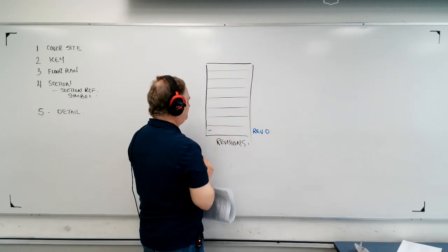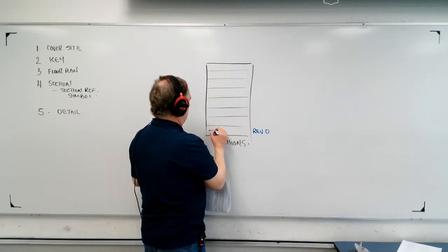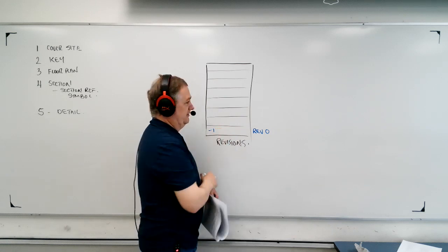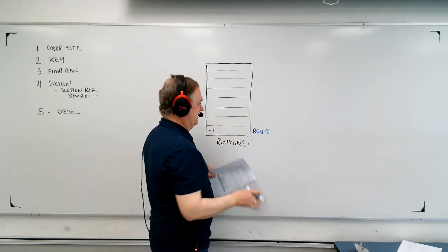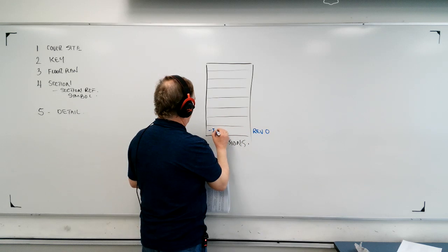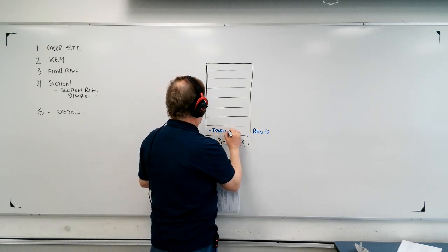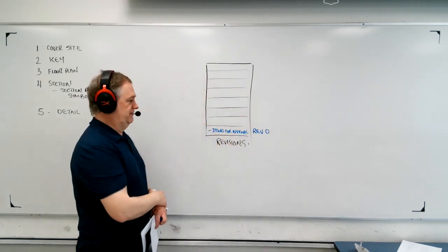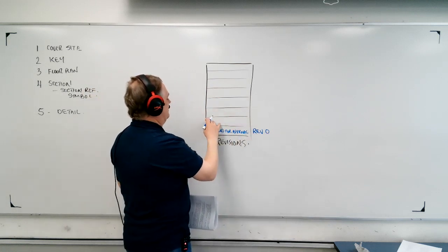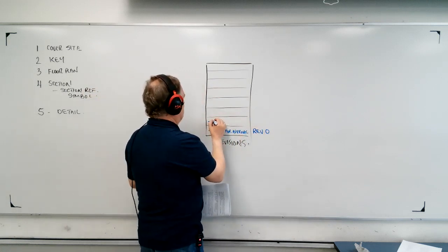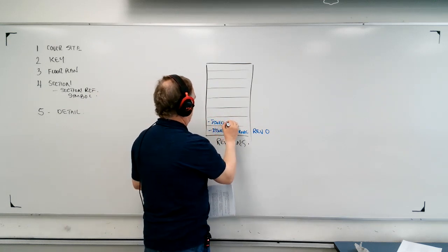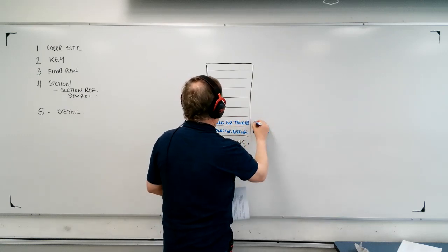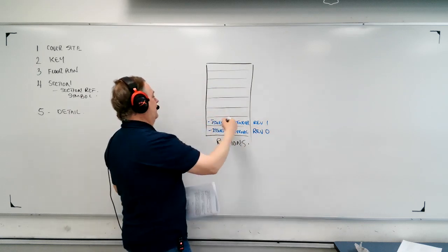And this will be, for instance, usually at the point where the engineers basically put everything together and put the plans together and put all their stuff in. So I would call this issued for approval. Quite often, the first revision is issued for approval. Then at some later date, after it's approved, it gets issued for tender, and that would be another revision, right? Tender. That'd be revision 1, and you'd have the date, and so on, and you work your way up.